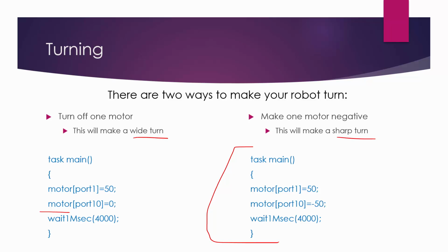So in this case, we turned the right motor off for 4 seconds, and that's going to make us move in the right direction. If you want to turn left, then you would make this guy 0 and this guy whatever power, and now the right wheels are going to continue to turn, the left wheels will drag, and they'll banana out to the left.